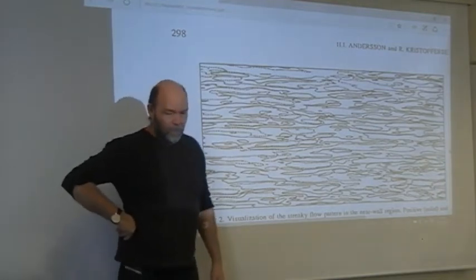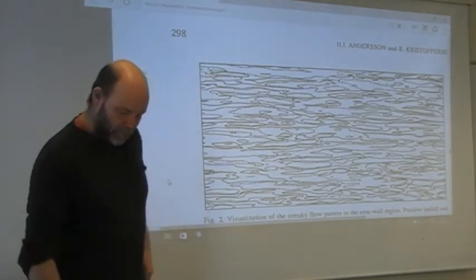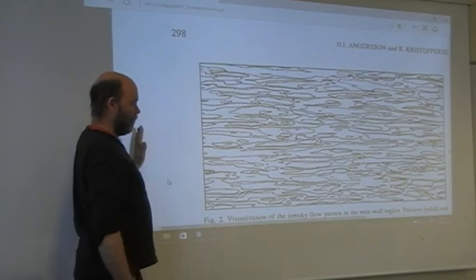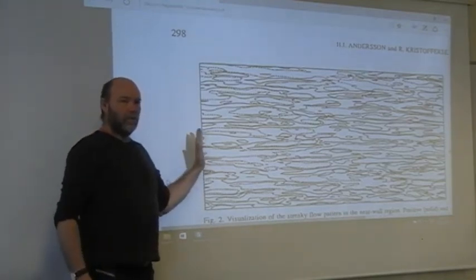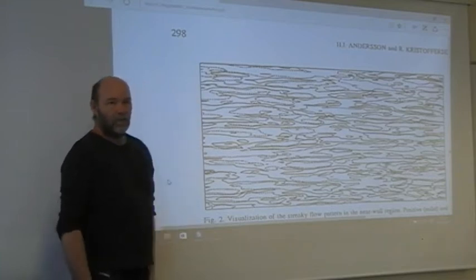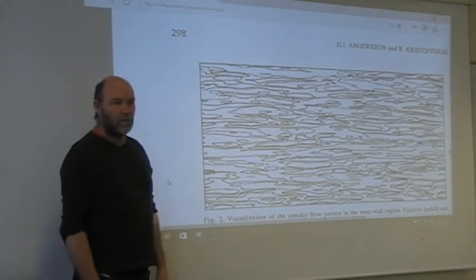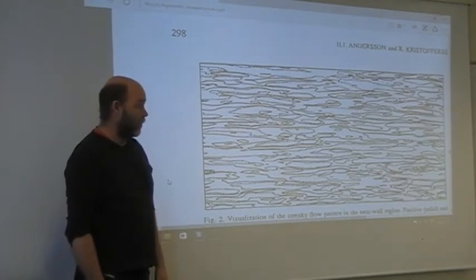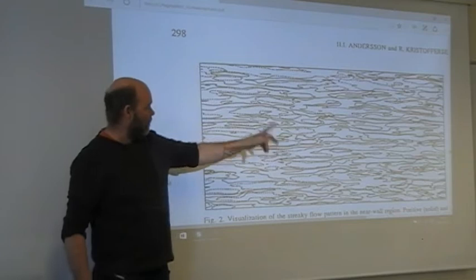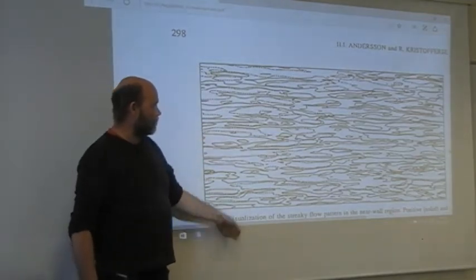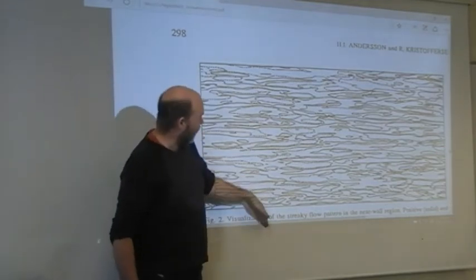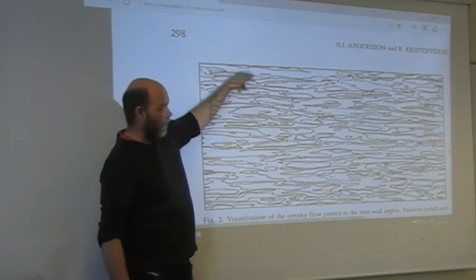Now remember the boundary conditions. What are we going to do here with the boundary conditions? Here is the inlet. And you have to send in a fully developed turbulent flow field, where the turbulent structures change with space and time. And you can't find it, of course, it's not possible. So what I do here, I use periodic boundary conditions. So I just set up a driving force, and then whatever goes out there, I send in here. Same goes in the spanwise direction. So if you have any structure going out here, you will enter up here, and vice versa.